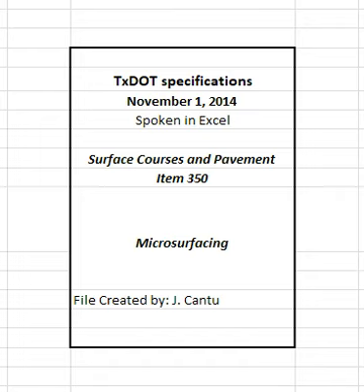Fill ruts 1/2 inch deep or deeper independently using a rut-filling spreader box that is at least 5 feet wide. Crown the spreader box to compensate for traffic compaction. Fill ruts deeper than 1.5 inches in multiple placements unless otherwise approved. Cure each lift 24 hours before placement of the next lift when using multiple placements. 4.14 Repairs. Perform full width repairs unless otherwise directed.